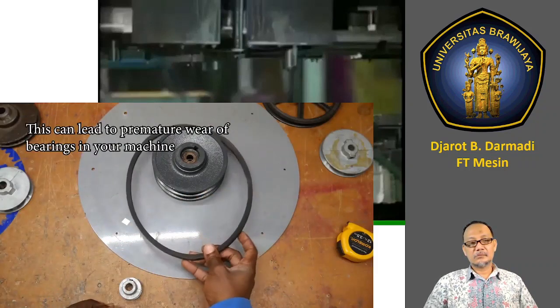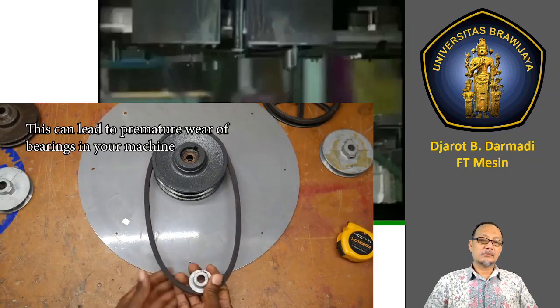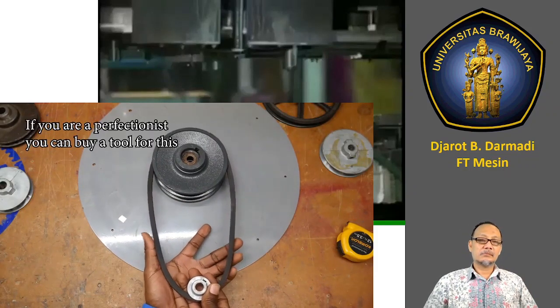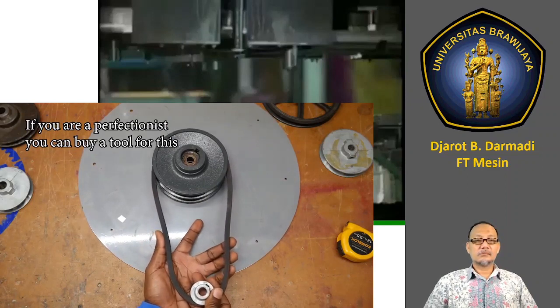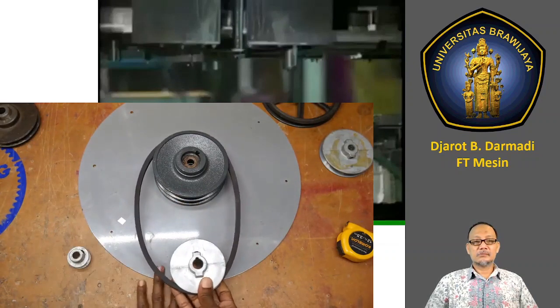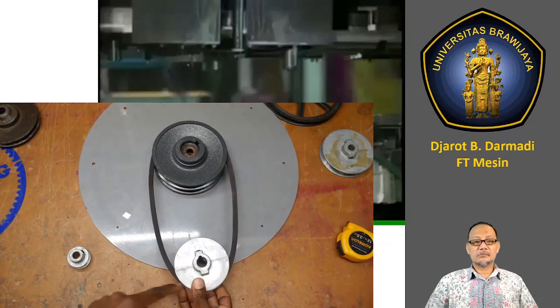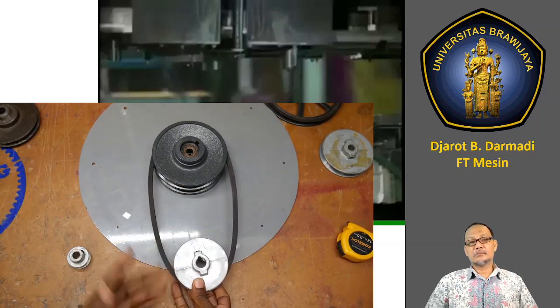You don't actually want your belt to be that tight. The best way to do it is you want it to be snug and then have just a little bit of slack. You should be able to flex your belt just a little bit. So we select a larger pulley. We try not to make it too tight, and this will allow us to get much more wrap. We can transmit more power and have less vibration.